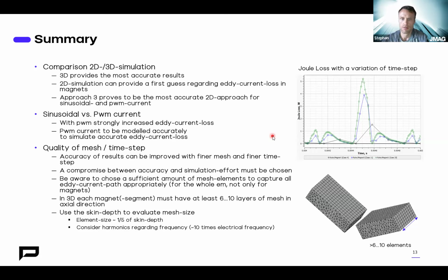And if you compare sinusoidal to PWM current, we can see a strong increase of the eddy current loss in the magnets. As far as I know, the first simulations that are done for an e-motor design are usually fed with sinusoidal current.